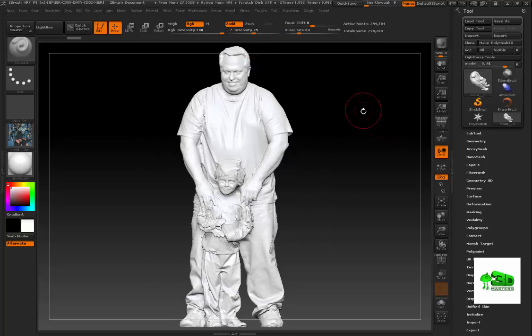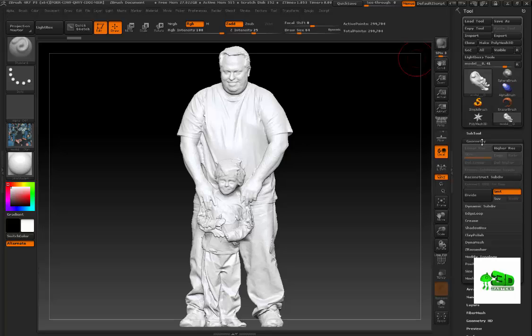So we're not done quite yet before we apply a texture. If you look up here, you'll see active points says about 299,000. Well, it's not enough because you need to have real detail when you project this back on there. So in my experience, you want to go to Geometry, and you want to divide it probably about 2 times. Now, where I see the most valuable point in projecting with the least amount of points and the most detail is somewhere around 8 million to 10 million polygons.